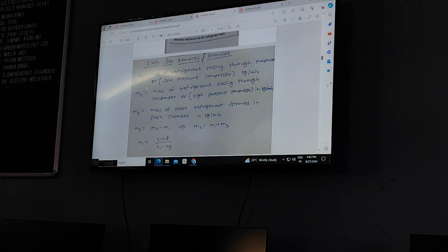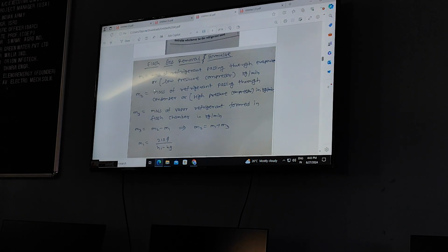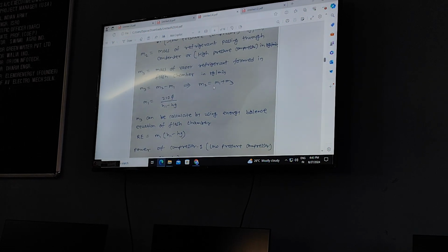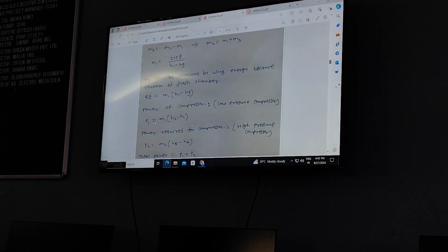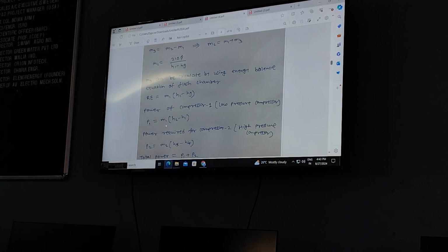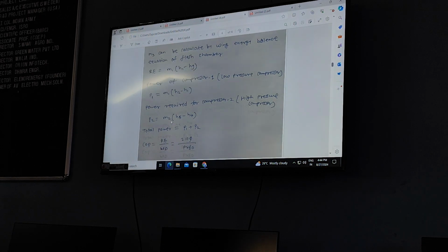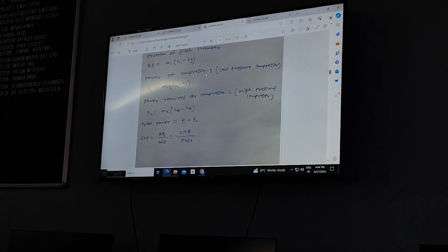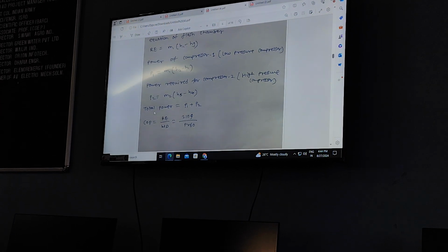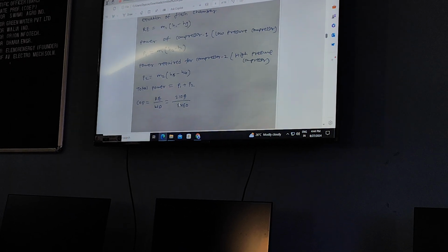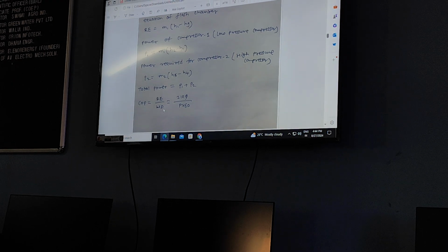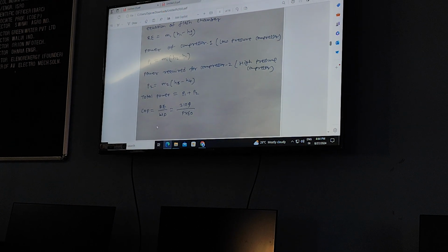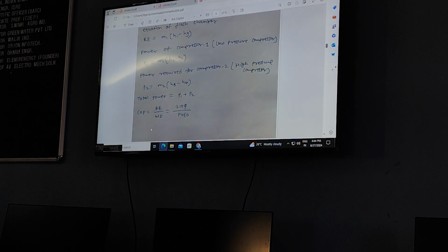Right? Here you need to write what is M1, what is M2, what is M3, the formula for M1, M2, then the formula for refrigerating effect, the formula for power. Here you can write divided by 60. P2 divided by 60. P1 is what? Power required for the first compressor. This is for the second. Total power. COP is what? Q divided by P into 60. Formulas are almost common. Only the M1, M2 formulas will differ.